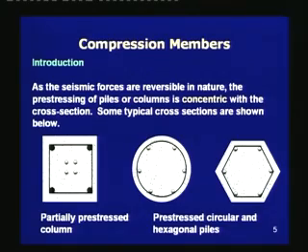Earlier, when we studied the behavior of axial members, we had known that prestressing is effective only when the concrete is under tension. In fact, prestressing may be harmful if the concrete is under compression because the compressive capacity of the member gets reduced. Thus, prestressing is applied to mostly tension members, but if a compression member is subjected to substantial moments along with compression, then prestressing may be meaningful.